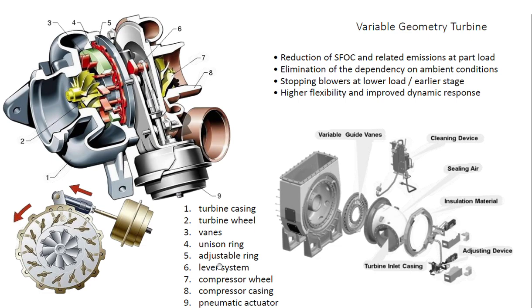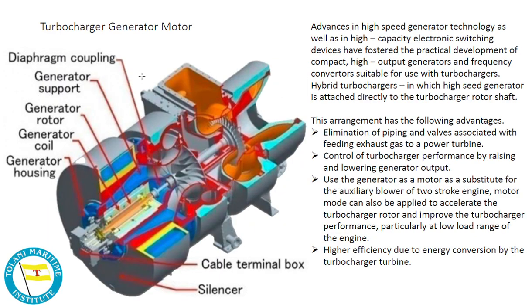Now let's go and see the turbocharger generator mode. Advances in high speed generator technology as well as high capacity electronic switching have fostered compact, high output generators and frequency converters suitable for use with turbochargers. We have the hybrid turbocharger in which a high speed generator is attached directly to the turbocharger rotor shaft.